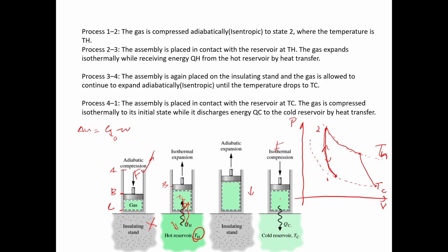We plug the cold reservoir, then apply force and compress it. So what will happen when you are compressing it? Compressing means it starts to increase the temperature, which means increasing the internal energy. That means an increase in the temperature. So again you have a temperature difference, right? So the temperature in here will be increasing larger than the TC, therefore you have a temperature difference, so therefore you can see a QC.